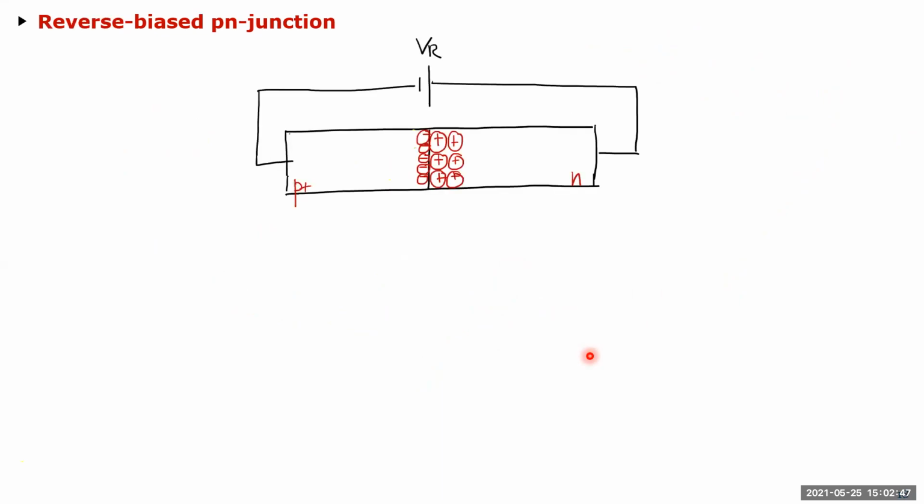Okay, the reverse bias, actually, from an IC design perspective, the reverse bias is more interesting. I shouldn't say more interesting, I should say everything is interesting, but more useful maybe, because pretty much like I said, if you have 1 million inverters in your design, then for each inverter you have 4 diodes, then you have diodes for your bulk and all that. So you're talking about at least 4 to 5 million diodes, which are all reverse biased. You're not forward biasing them, you're just reverse biasing. And they're obviously parasitic in nature because that is what you get from those active devices.